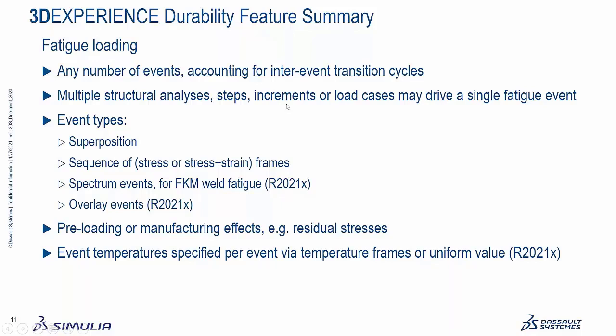In FE-Safe, those are called high frequency events, but ironically, some people would use the high frequency event for the low cycle and use the regular event for the higher ones. But anyway, the preloading effects, including residual stresses and so on, can of course be included. We recently added temperatures. It allows you to specify temperatures either as a uniform value, or you can specify a temperature frame that you want to apply to each event.